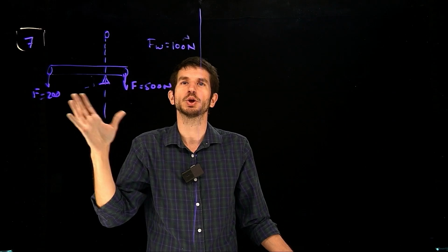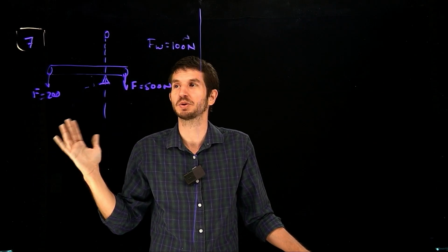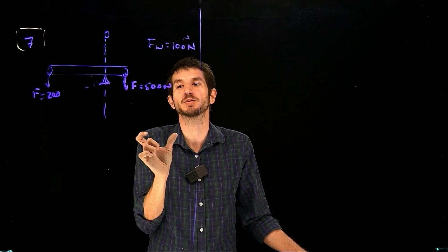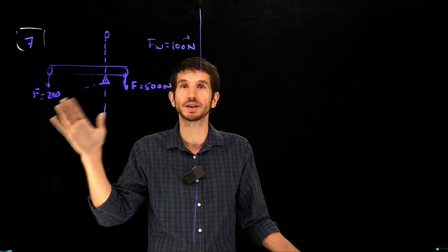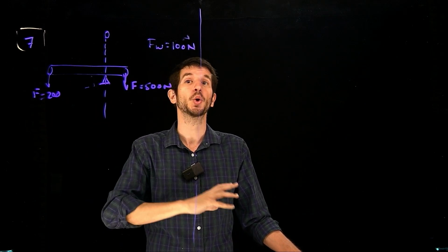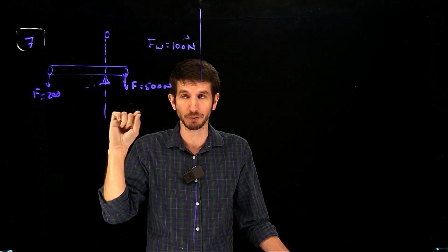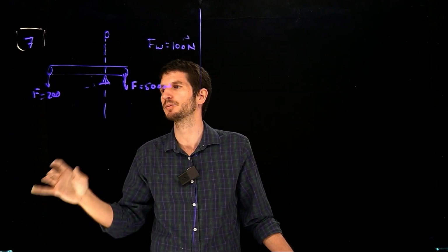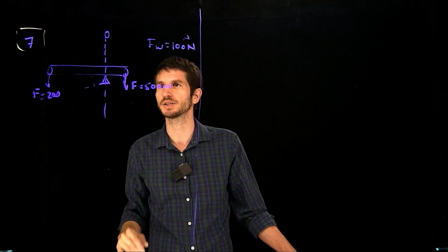But an object that is not rotating has no axis with respect to which it is rotating. So you cannot say it's not rotating with respect to this axis but it is with the other one. If the bar is in equilibrium, it's not rotating about any axis. So I'm free to choose whichever axis I want. Again, this is the important thing: if it's in equilibrium. So I can choose this as the 0, and then define the distances accordingly.